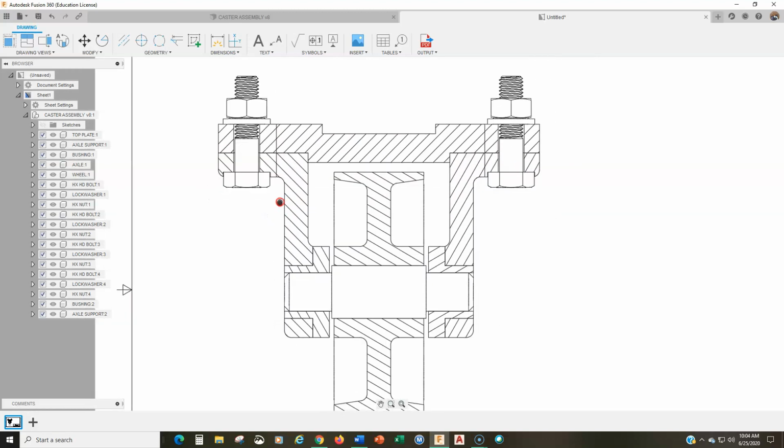All right, now let's adjust our section lines. So remember, there's two ways that we can adjust our section lines. Okay, and this is not just Fusion. This is according to the section view standard. You're allowed to adjust the section lines by direction and by scale, or size. Small parts need a smaller spacing on our section lines, and adjacent parts should not have the section lines that go in the same direction.